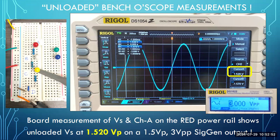Okay, slightly higher. And you may find some of these variances that will occur between your signal generator and what the oscilloscope actually reads. There may be some tiny, tiny fraction of a difference. So on my signal generator, it says 1.5 volt peak, which is 3 volt peak to peak, and the oscilloscope actually measures something slightly higher. So we get a bonus of 0.02 volts peak, 2/100th of a volt extra. Never bad when you have extra.